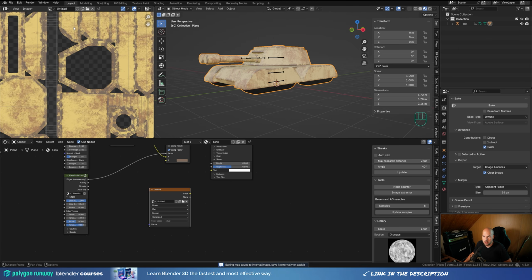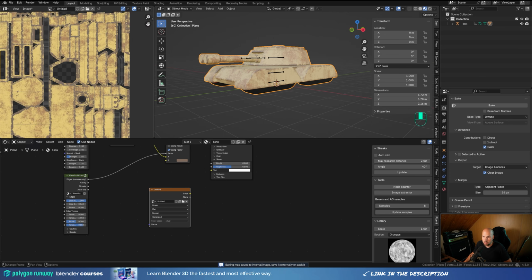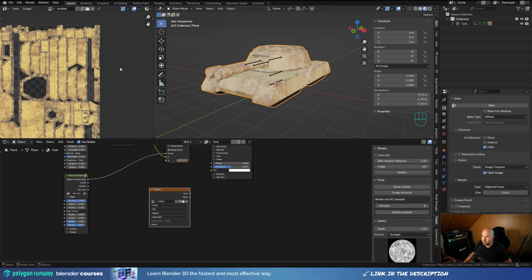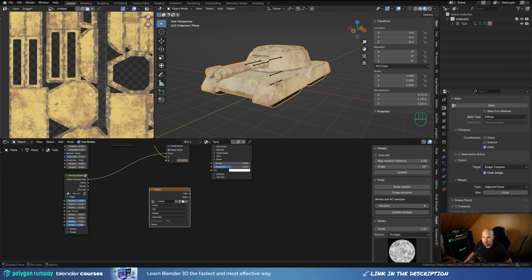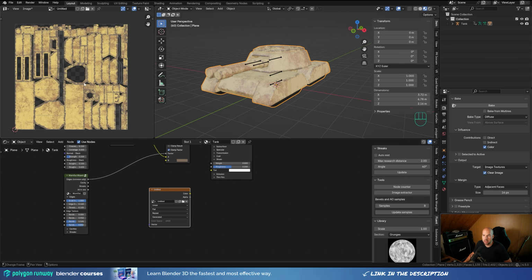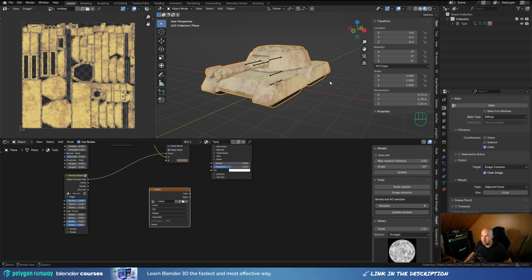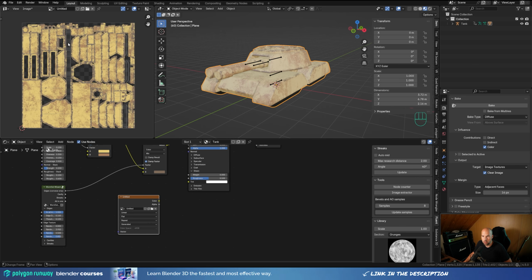And now you can see the result right here. All this procedural stuff that we made with the add-on is now baked into the texture. So again, this was not about how to create this particular effect with this grunge, whether it's with using the add-on or not. This is about this process where you create a texture slot, and whatever you have here, you UV map it, and then you bake your color results or whatever channel you want to bake into the texture